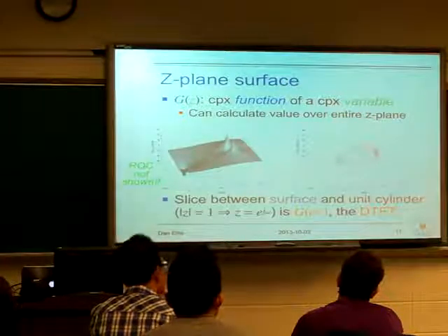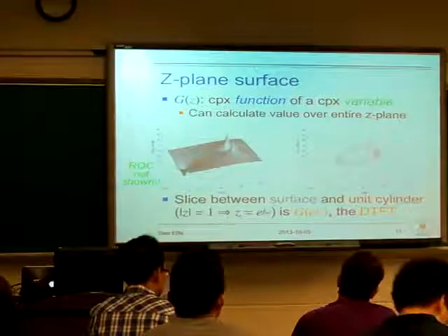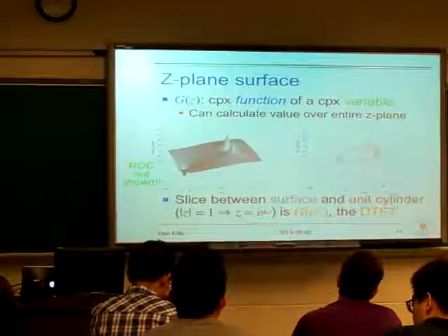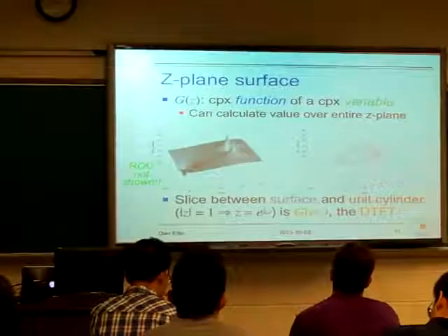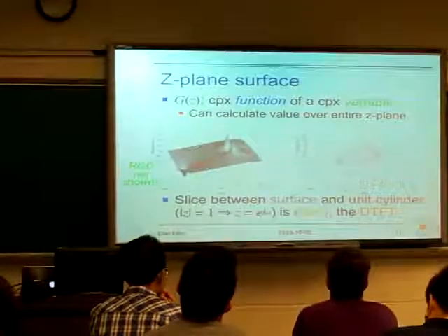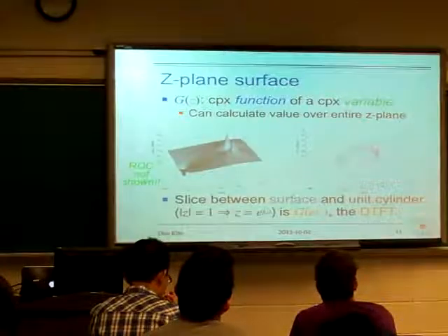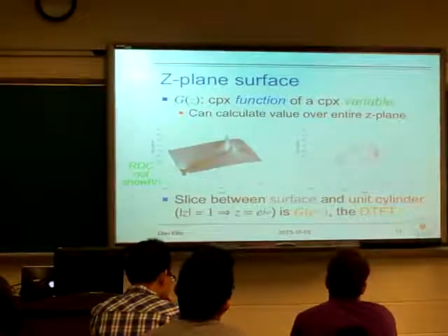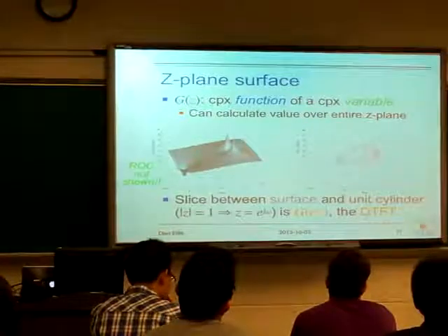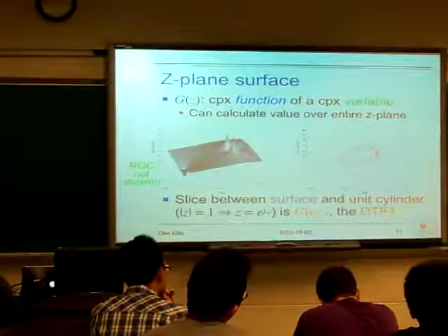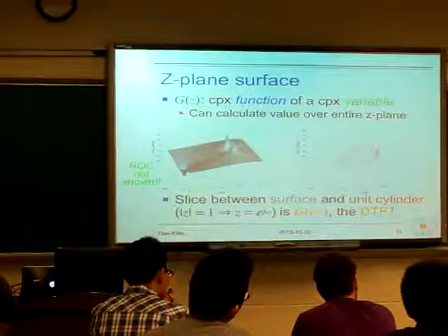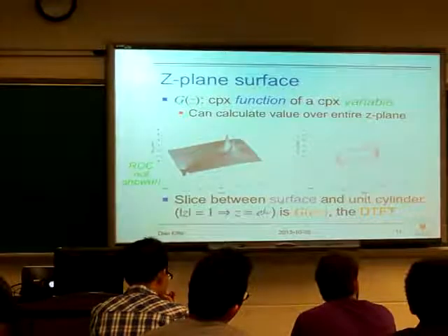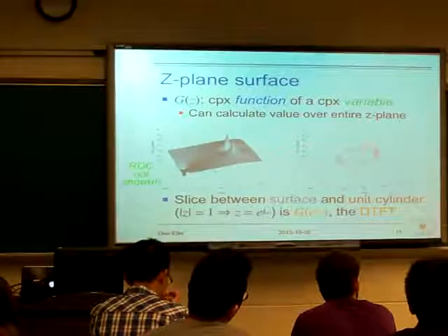So that's what we're saying, that by evaluating the z transform for this particular set of values of z, which is the unit circle, right? Because this thing has a magnitude of 1 and an angle of omega. So this is a function over all possible values of a complex value, so it's all possible values on a Cartesian plane. But there's a subset of these, a one-dimensional subset, a circle in this case. And when we evaluate those, we just get this thing.